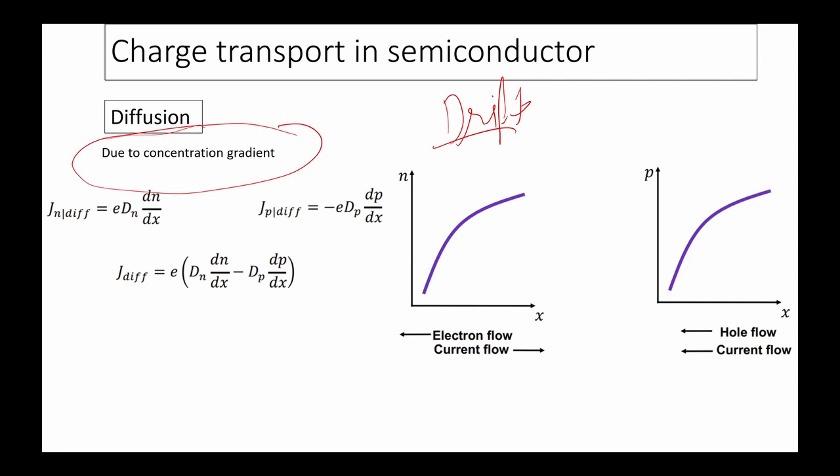You need to understand how semiconductors are doped, though it is not that much required, but I will tell you. Let us say this is a piece of semiconductor. When we dope the semiconductor with phosphorus, we can spread a layer of phosphorus atoms and increase the temperature. The phosphorus atoms will diffuse inside. This is known as the diffusion process.